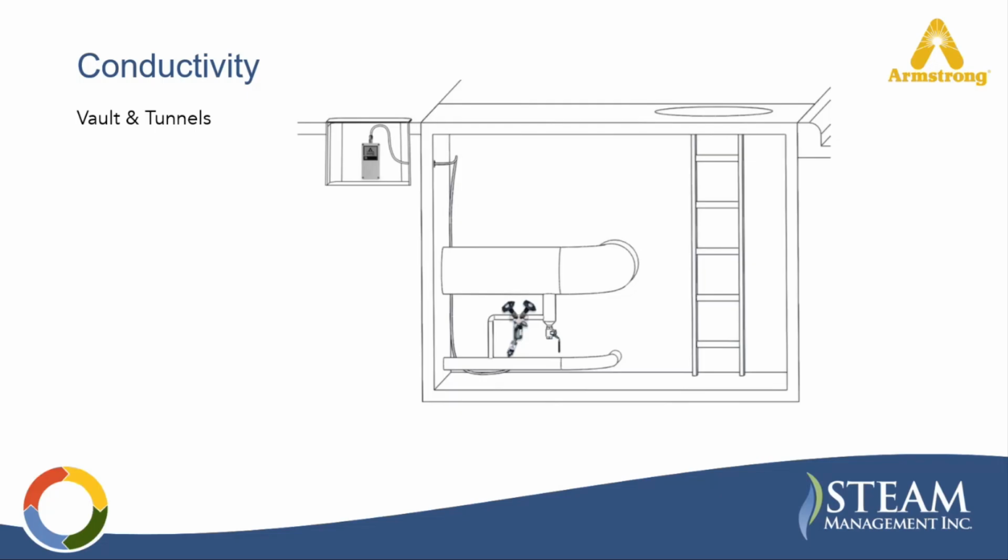Here we have a picture of a typical installation in a vault or a tunnel for this type of remote conductivity unit. In a typical vault application, the conductivity probe is installed directly into the bottom of the Armstrong inverted bucket trap located inside the vault. The transmitter is then wired to the probe. However, instead of placing the transmitter inside the vault itself, we mount it in a nearby accessible location, and this provides several advantages.